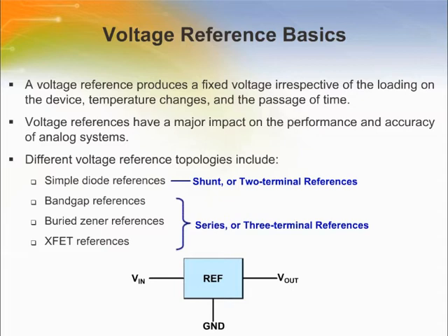and V-out. The series types have the potential advantages of lower and more stable quiescent current, standard pre-trimmed output voltages and relatively high output current without accuracy loss. However, shunt or two-terminal references like diode references have more flexibility regarding operating polarity but are more restrictive as to loading.